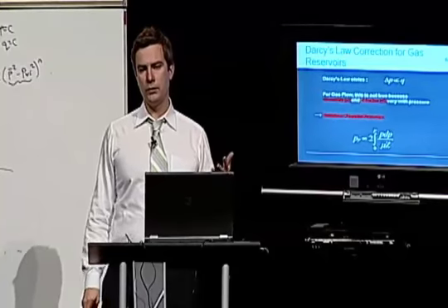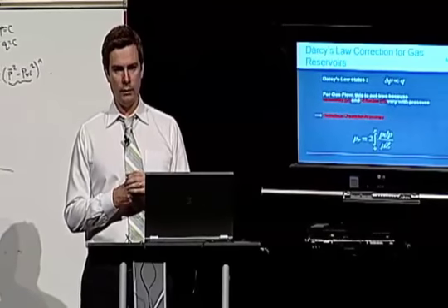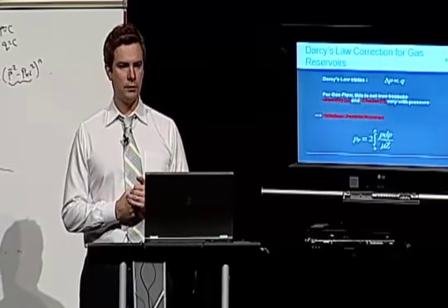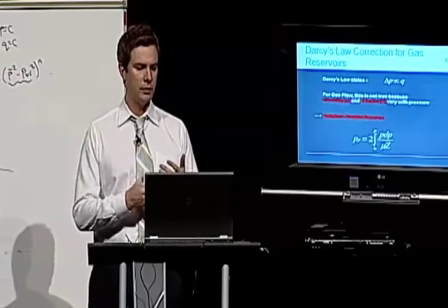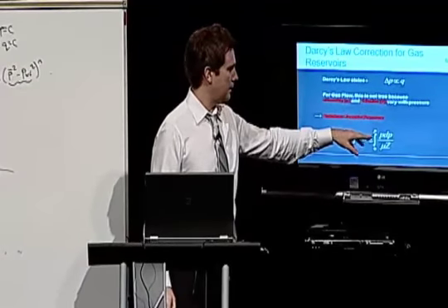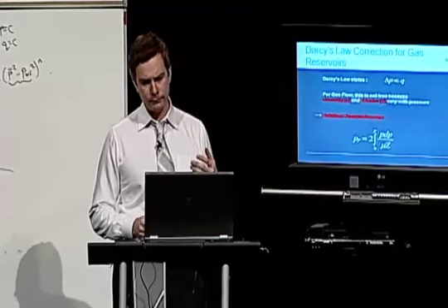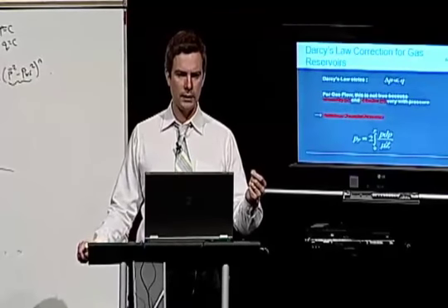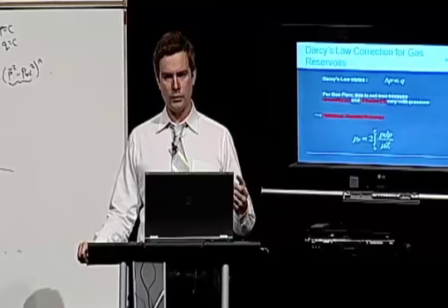And one of the ways you can do that is use a nonlinear scale that plots the pressure instead of the pseudo pressure. So there's all kinds of tricks that we invoke for doing that. But this is an easy correction to make. And pseudo pressure has been used in the well test literature for many years. So it's not a new concept.